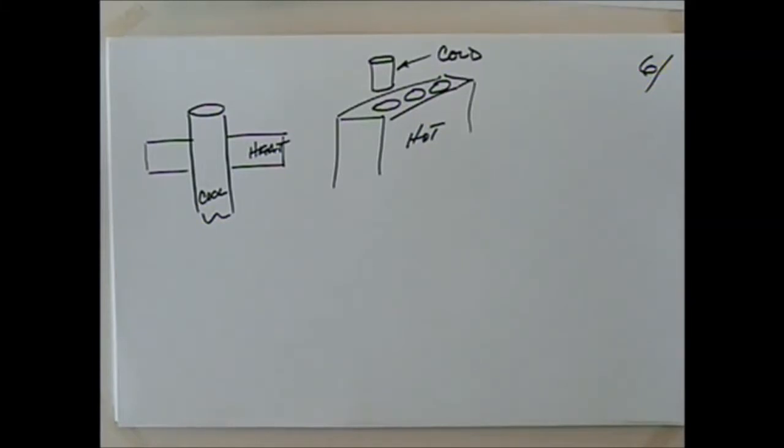So this is used quite a bit. And again, we can use this to our advantage. It sometimes can be difficult when we look at an exhaust manifold or something like that. It will expand more than what it's bolted to and break the bolts. Really high-quality industrial engines usually have some sort of a clamping mechanism rather than actually just bolting it down. There's an interesting example if we look at thermal stresses, the Liberty Bell.